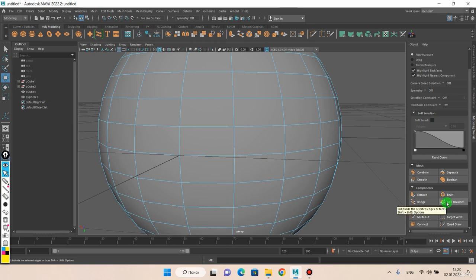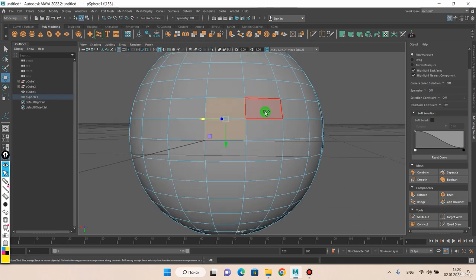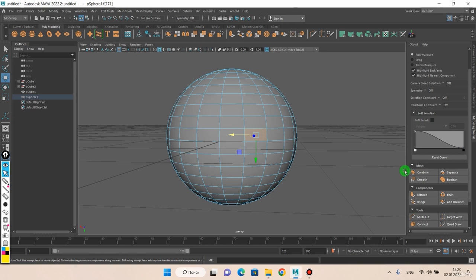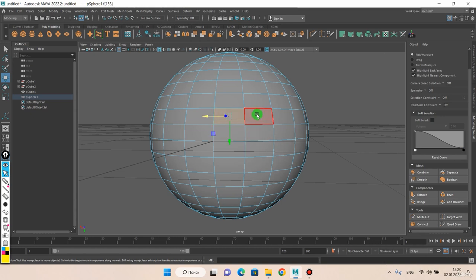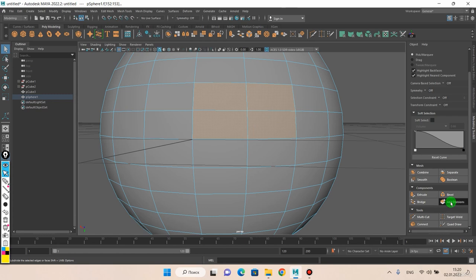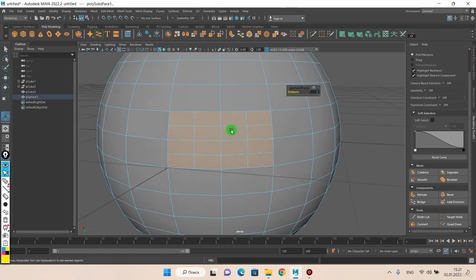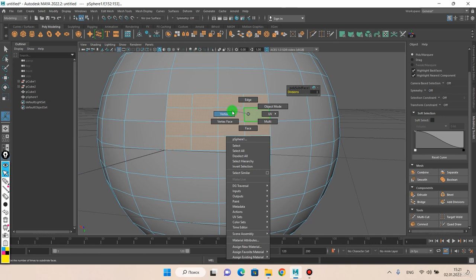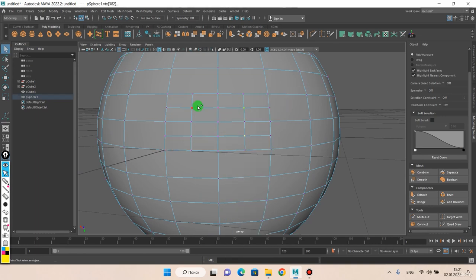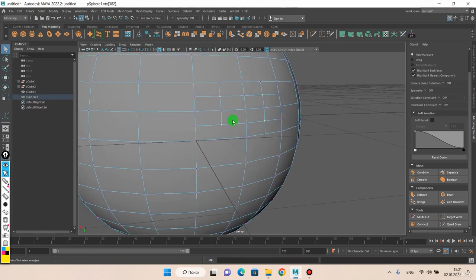And we have one more command right here. It's add divisions, and with this command you can manually add subdivision to polygons. Works basically the same as a smooth, but for the components. So we just click on it, and here we have our polygons divided 1 or 2 or 3 times, as many as you want. And of course, these new components we can use to our advantages.